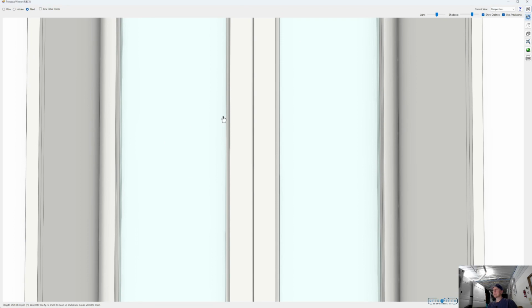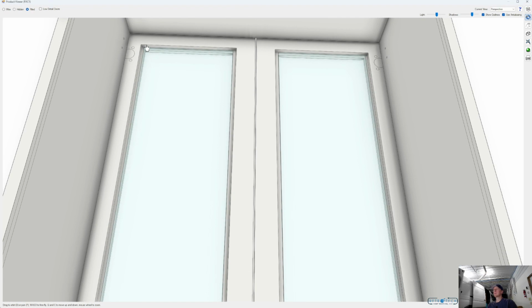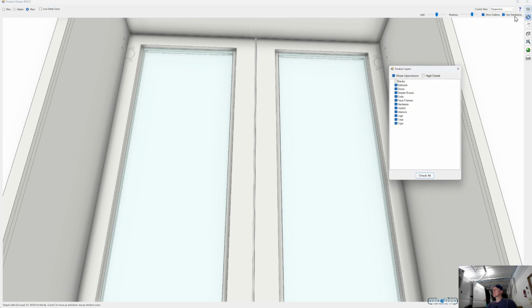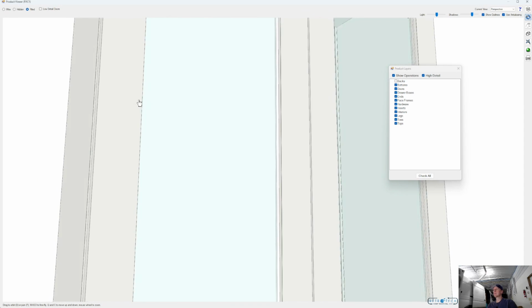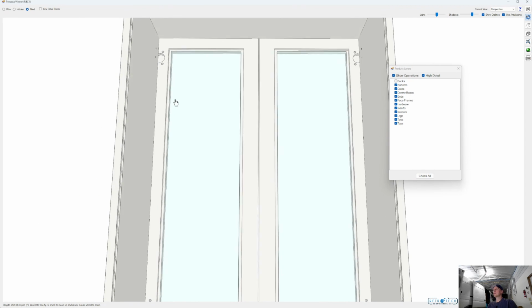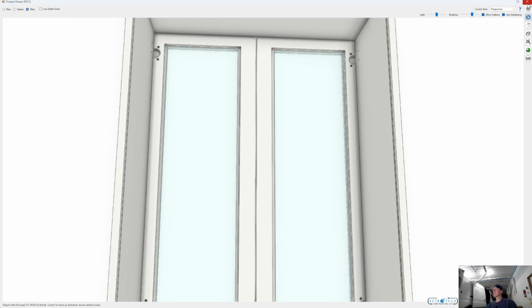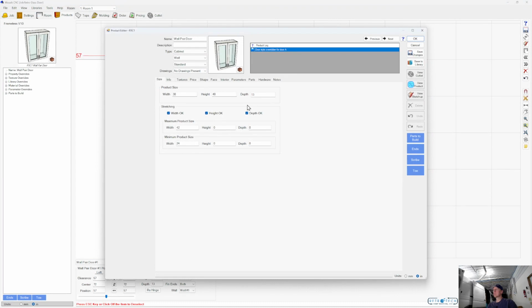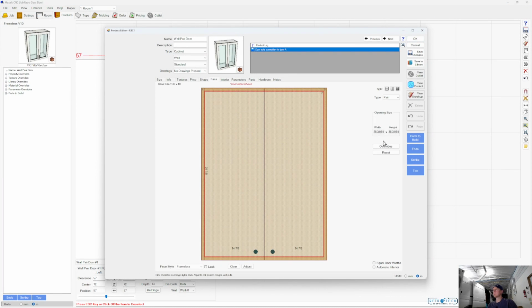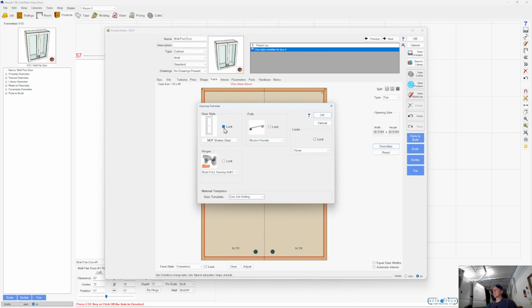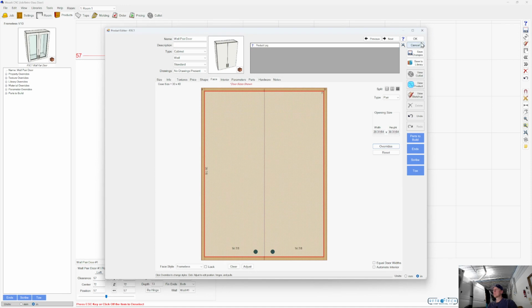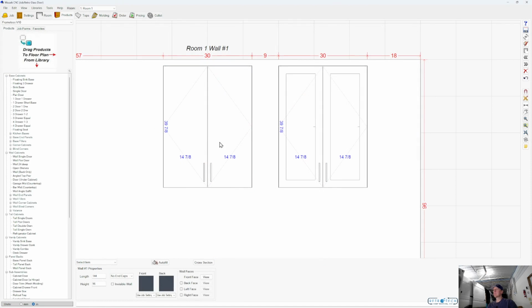You see in the back it has that rabbet out, and mine is 3/8 inch wide, and I'm at 7/16 deep because I have a 5/16 pocket on my standard shaker. But you can do whatever you want for yours. So let's just start over with this door. Double click on this. We'll go into the face. Override this. Right now I have it overridden. We'll just take that off. So we're back to just a slab door here.